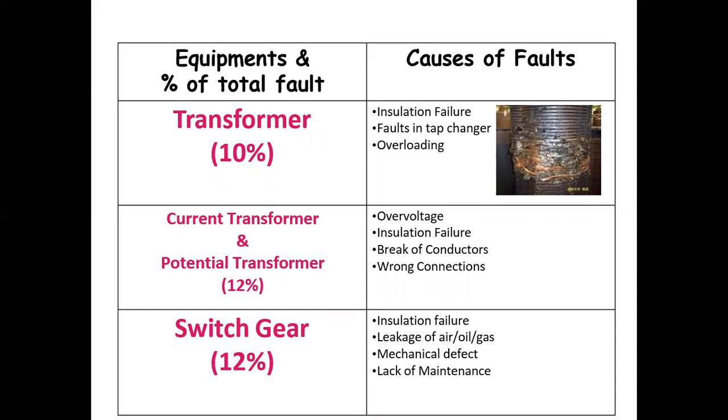Then switchgear equipment, causes of fault: insulation failure, leakage of air, oil, gas, mechanical defect, and lack of maintenance.